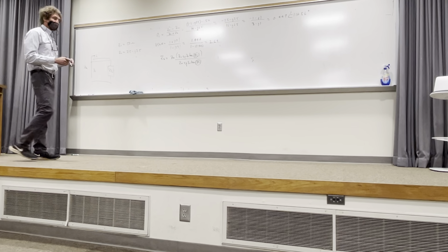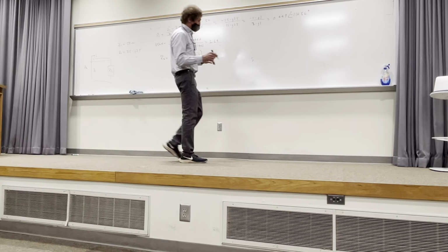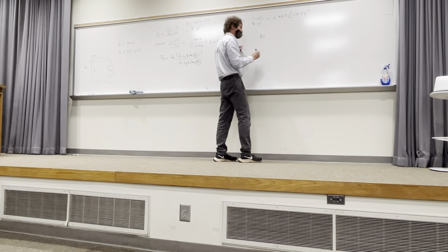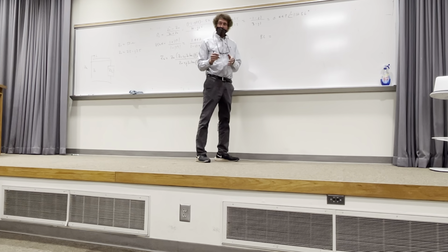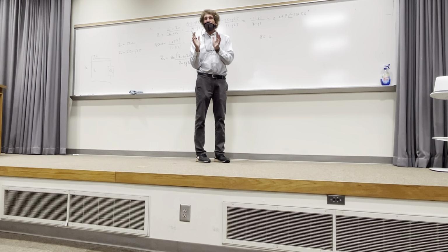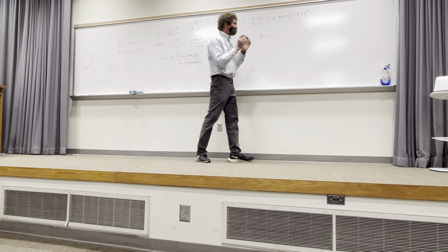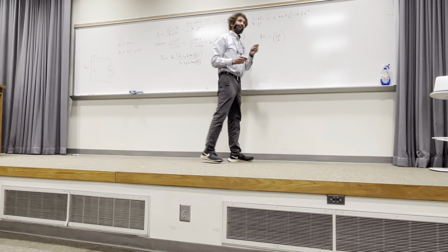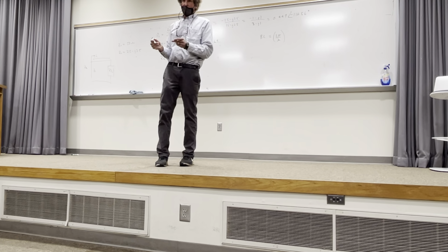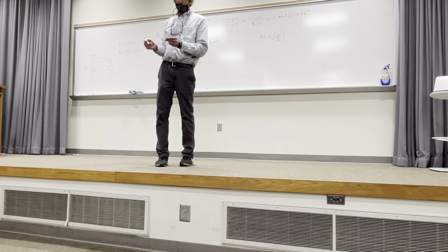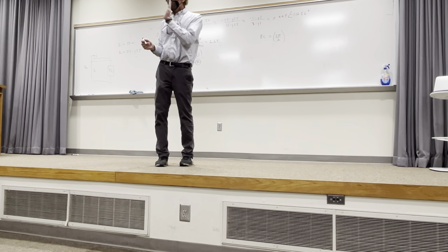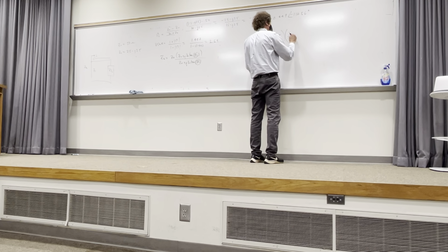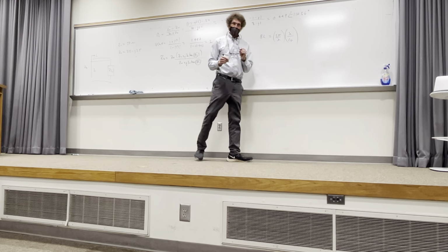So if we take a look at beta, now just listen to me. When we're looking at the term beta L, well, beta is 2 pi over the wavelength. Do you all hear me? So make sure that rings true. So it's 2 pi over the wavelength. Here the length was given in wavelengths, not in meters, right? It was 1/10 of a wavelength away, wasn't it? So they want the impedance when you're 1/10 of the wavelength away. So that would be lambda over 10. Do you all follow me?